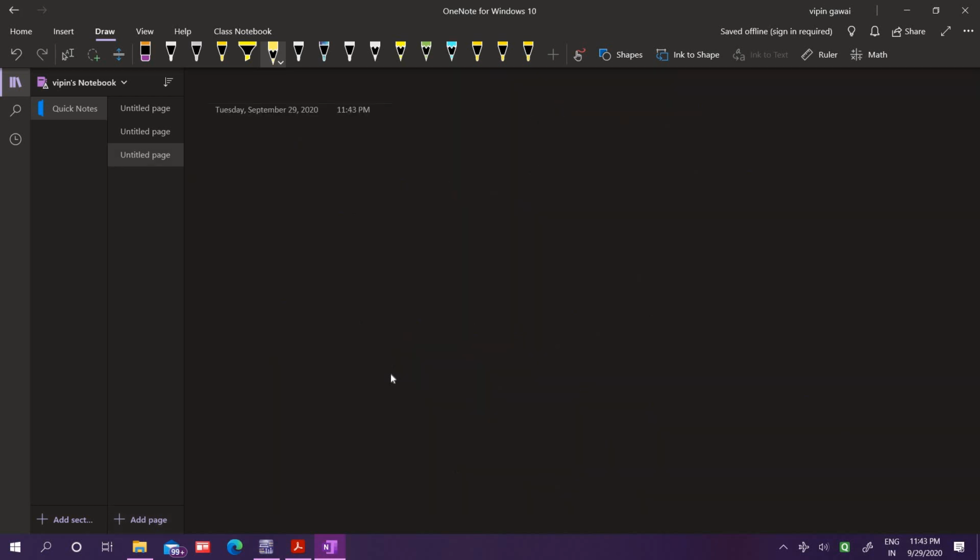Now we can find the AVS. AVS is equal to AV into RI upon RI plus RSG. We know the AV value, and we know the RI value and RSG value.